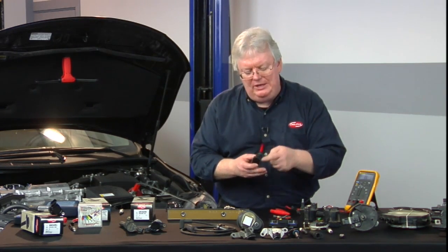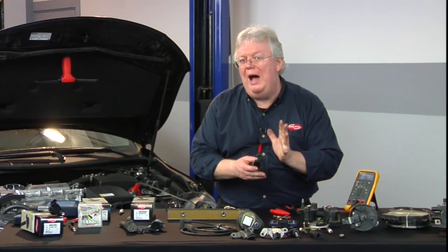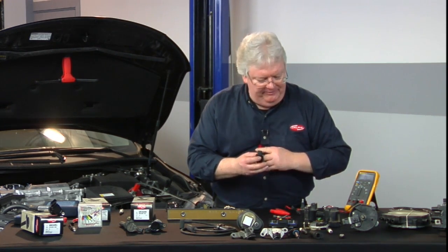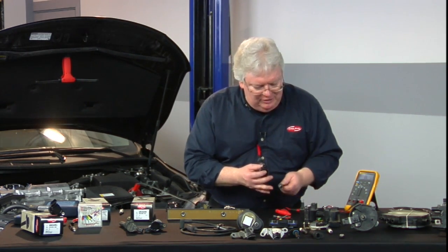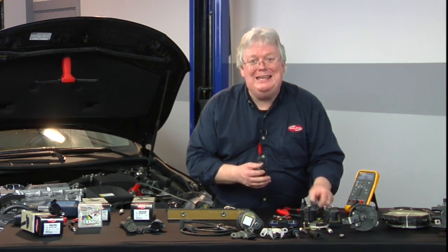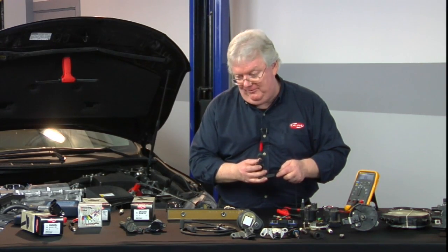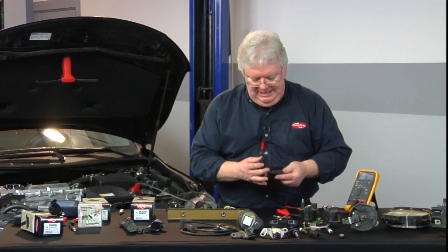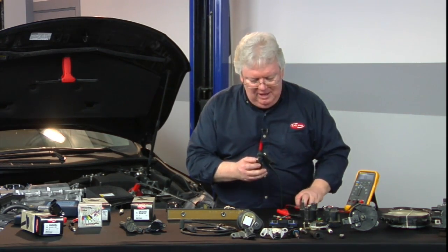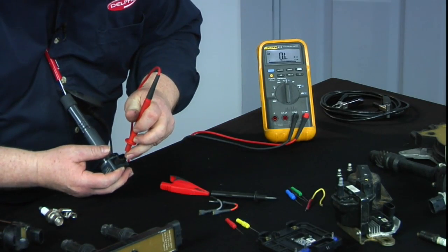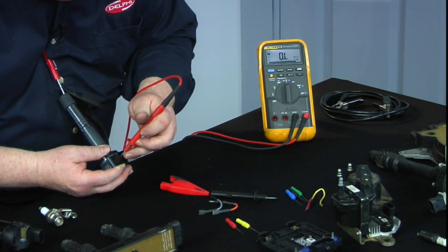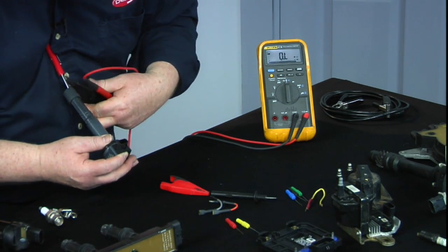A lot of these modular type coils, more than 2 wires, 3 and 4, have blocking diodes to prevent you from even trying to do what we're trying to do right here. So what I'm saying is, if you don't have 2 wires, like the Ford Coil-On-Plug, you're not going to have much luck doing any resistance bench testing on either the primary or the secondary winding. That's an OL, that's an OL, that's an OL, open, open.